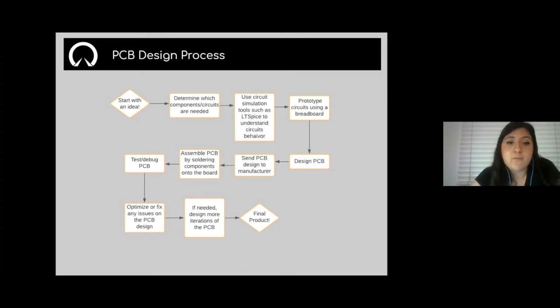Next, you should focus on prototyping, and that should be more on the semi-permanent board testing. I'm pretty sure you guys are familiar with breadboards, and that's really ideal because you can adjust different components and wiring and really understand what's going on. Some useful tools during this phase would also be using multimeters, power sources, oscilloscopes, and function generators if you need an oscillating function. And during this phase, you need to think about whether your real life testing actually matches your simulations. Are the waveforms correct? Is the output voltage correct? What about the current? And then you could head straight into designing. You can use any of the software that we've mentioned before, or any other ones that are more accessible to you.